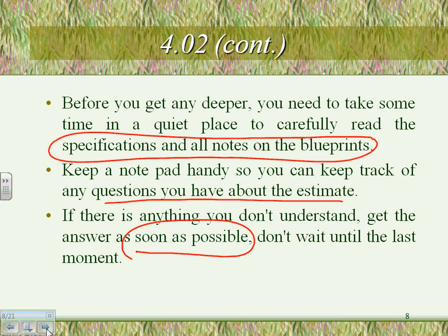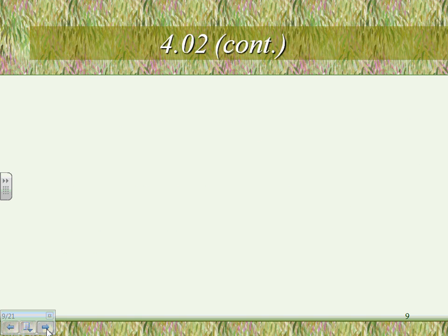You don't want to sleep on it. I've never done estimating on a larger project, guys. But if you have any problem, what I would do is write them down, and don't sleep on them though. Don't write them down, go home and sleep, and say, no, we'll do it. Call them tomorrow. Immediately after you're done with all your questions, went through them, write them down, call the engineer, the architects, get your answers as soon as you can.